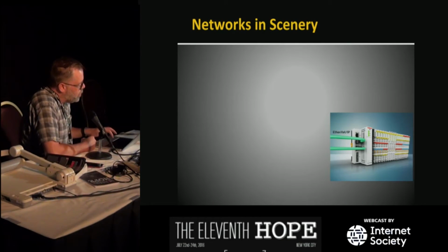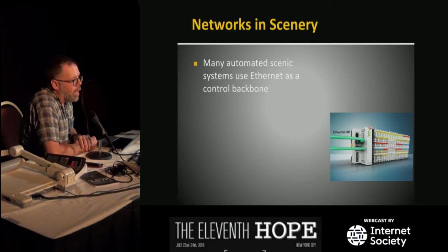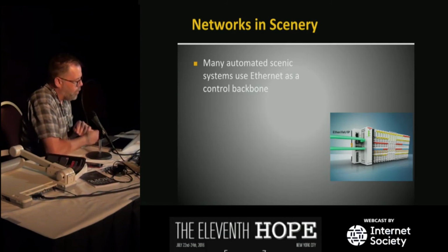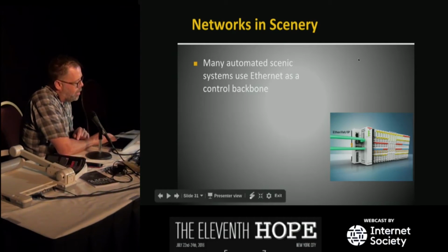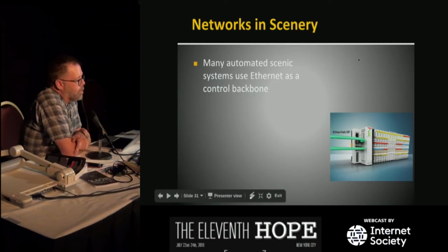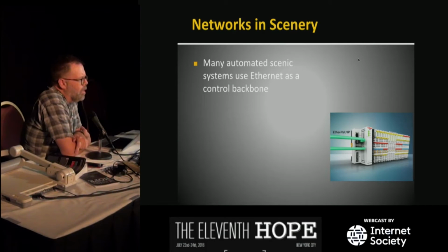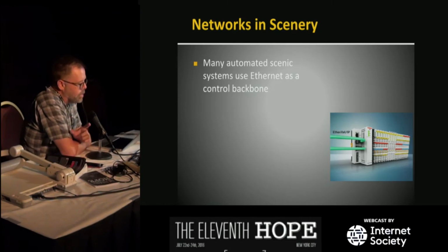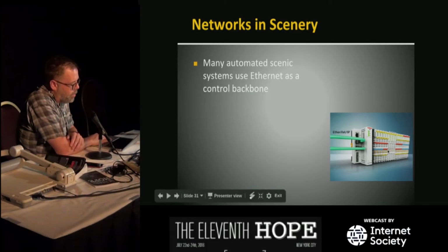Scenery. So a couple of things in scenery. A lot of automated scenic systems. We use Ethernet as a control backbone. This is a system called Beckhoff, very widely used in theme parks, but also as the backbone of companies like Stage Technologies, Tait Towers. Those kind of guys, or sorry, Tait, not Stage Technologies, but they're moving to it, use this. And then just using standard off-the-shelf Ethernet infrastructure, sometimes they have a slight variant of that I'll talk about in a minute. And then this kind of box can provide whatever I/O you need.